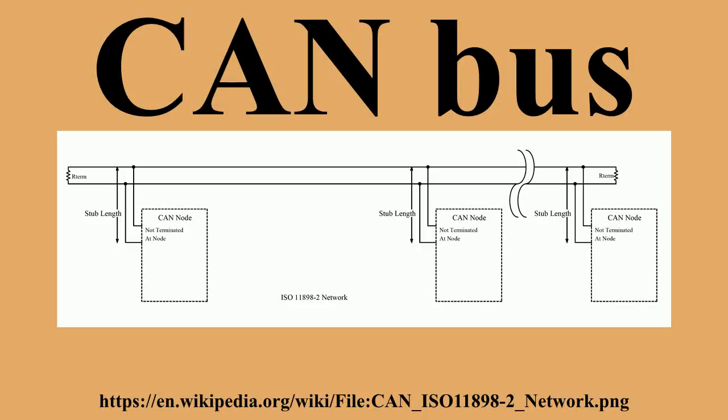Transceiver, defined by ISO 11898-2/3 medium access unit standards. Receiving: it converts the data stream from CAN bus levels to levels that the CAN controller uses. It usually has protective circuitry to protect the CAN controller. Transmitting: it converts the data stream from the CAN controller to CAN bus levels. Each node is able to send and receive messages, but not simultaneously.